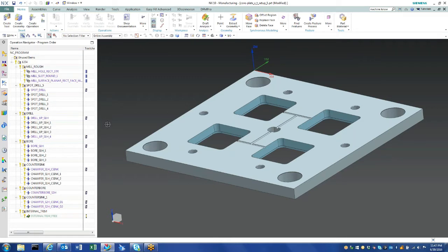So now also this machining knowledge database, what is that? Well, you have a database that's preloaded in the machine that contains rules for all of the operations. For this hole here, the system looks and says, okay, that's a step 1 hole because it only has one step in it. A counterbore hole would be a step 2 hole, and so on, step 3 hole and 4. It's just the different diameters in there. It can even be a step 2 hole thread, so that'd be a counterbore threaded hole.